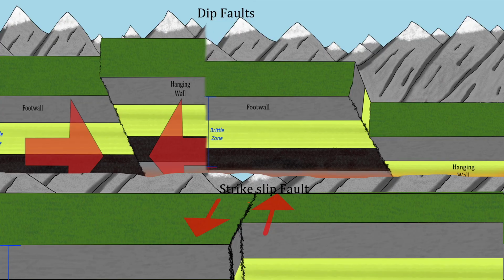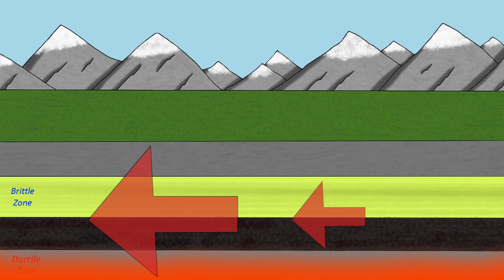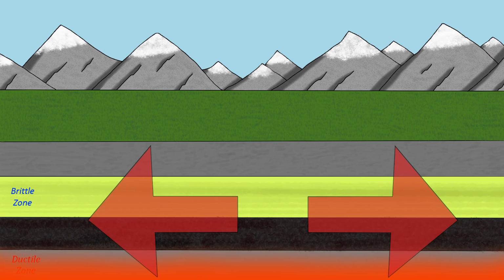Fundamentally, there are three kinds of fault system. Two kinds of dip fault that are formed through vertical movement within the fault system, and slip faults, which are formed under horizontal movement. We'll cover the dip faults first. Normal faulting occurs when a section of brittle rock is placed under extensional stress from opposing vector directions. Or these force vectors could be moving in the same direction but at different velocities, with a faster block traveling ahead of a slower one, leading to the rocky body with faster velocity pulling away from the slower section of rock. The differences in force vectors will place the rock under extensional stress as it's pulled apart.